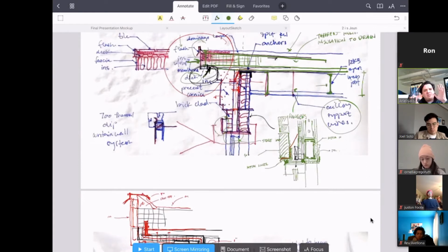So you almost have to look at it really critically, just like I started looking at here. I say, what happens on the soffit? What happens with the insulation? Right here, another example for you, Joel. Notice what happens here, and I'm sure you guys are going to have this. Notice what happens with the... This is his Y flange, right in here. So in reality, the Y flange is here.